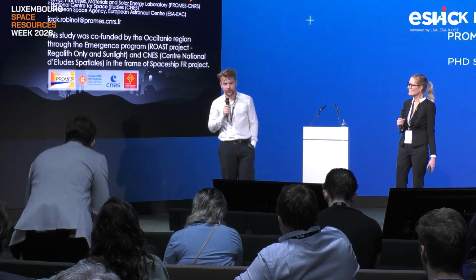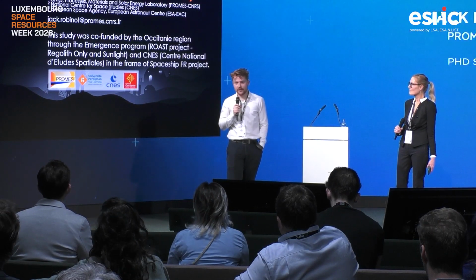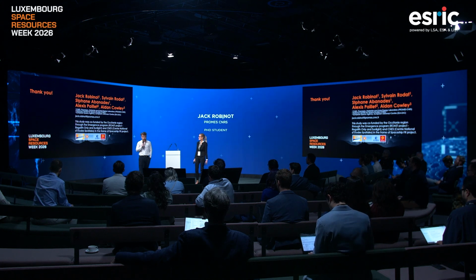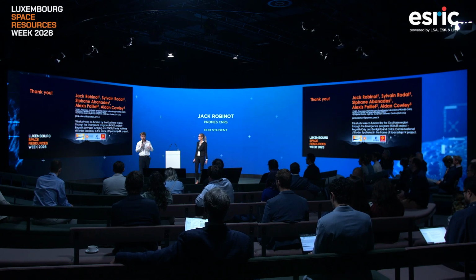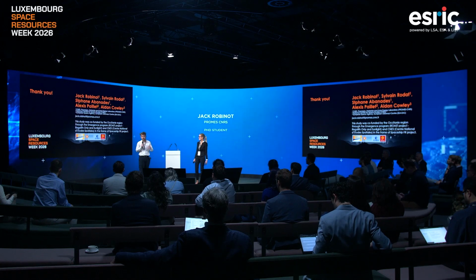Yes, thank you for your question. So the first question, it's quite challenging to do some measurement on the emissivity, and there is a lot of stuff that is happening inside the molten regolith. When the regolith is molten, it becomes a semi-transparent medium, so we don't exactly know what is happening, and there is some strong difference between the various regolith simulants in their optical properties. So yes, we try to do some measurement, but it's really hard to draw some conclusion because we are not able to do measurement at high temperature and in molten state. We did some measurement on the glass that we obtained after the pyrolysis and on the regolith.